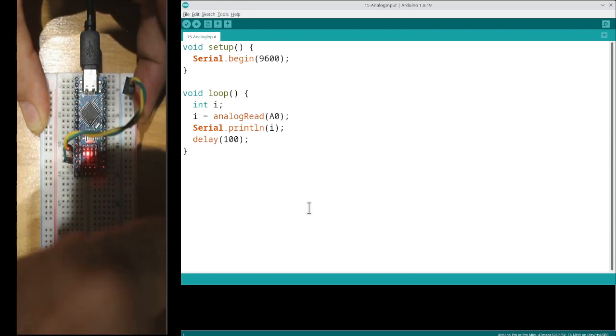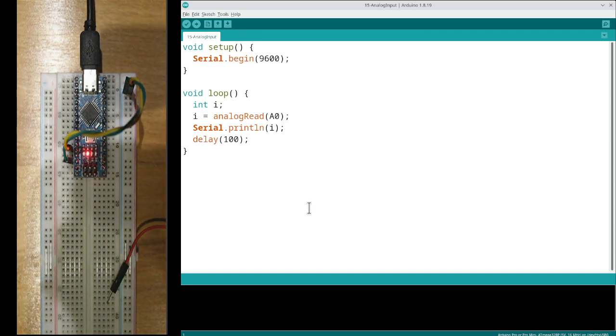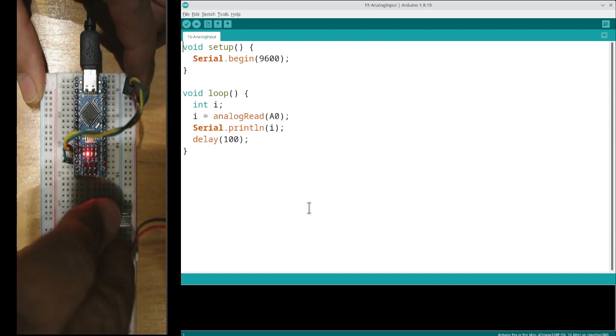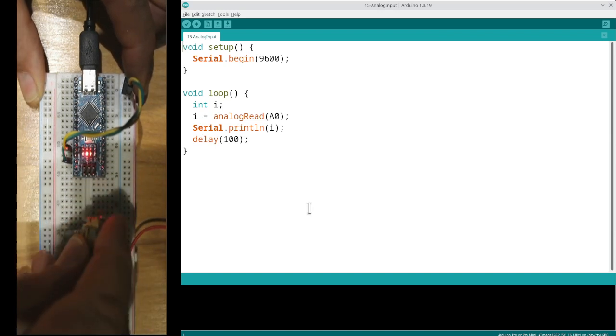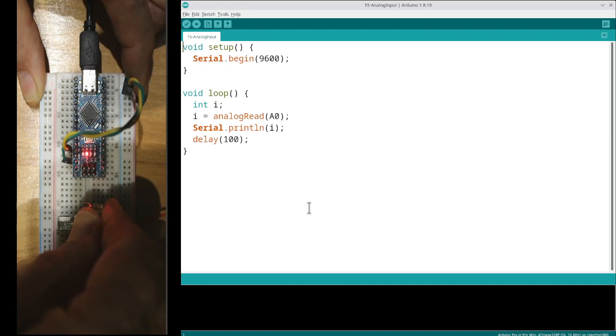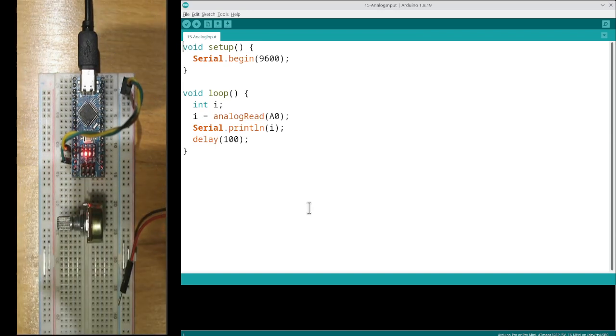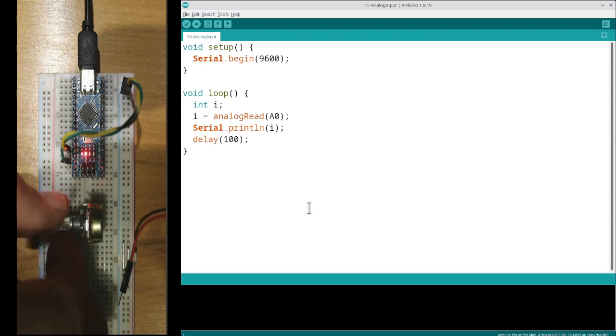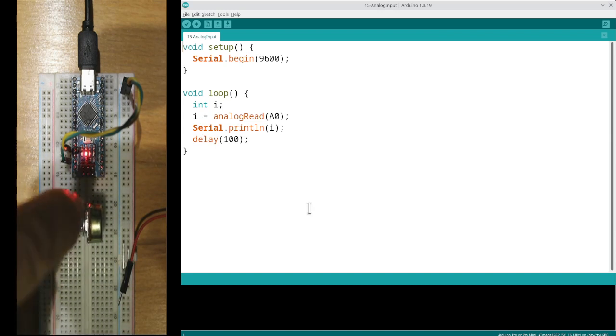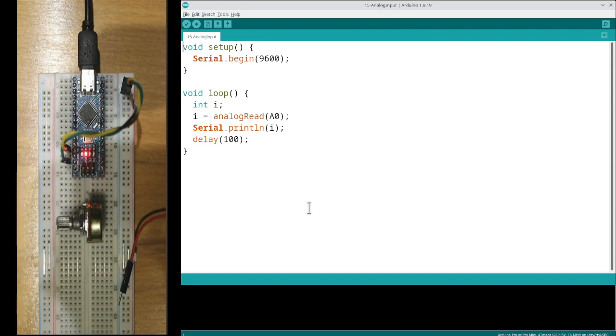And now we had an analog here with our little potentiometer, right? Let's put him in the other way around. Okay, so remember I said between the one pin and the other pin there's voltage being dropped all the way along, and so the middle pin, the wiper, actually has somewhat of the voltage depending on where this has been turned, and that's very typical of something analog.